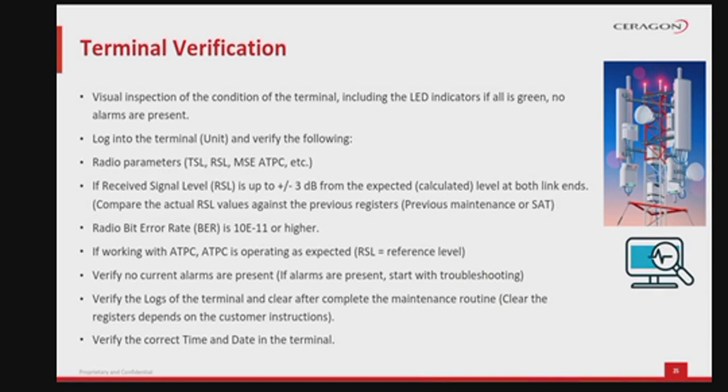Continue with the physical verification of the terminal's condition, including the fact that LED indicators should all be green, meaning no alarms are present on the element.